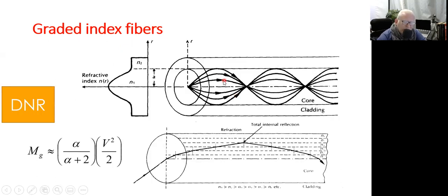Herein, we found that the total internal reflection can happen inside the core material. Not all the signal will reach the core cladding interface due to the variation in the refractive index inside the core material, so that the total internal reflection occurs at the point at which the condition sine phi, the total internal reflection angle, equals n2 over n1.